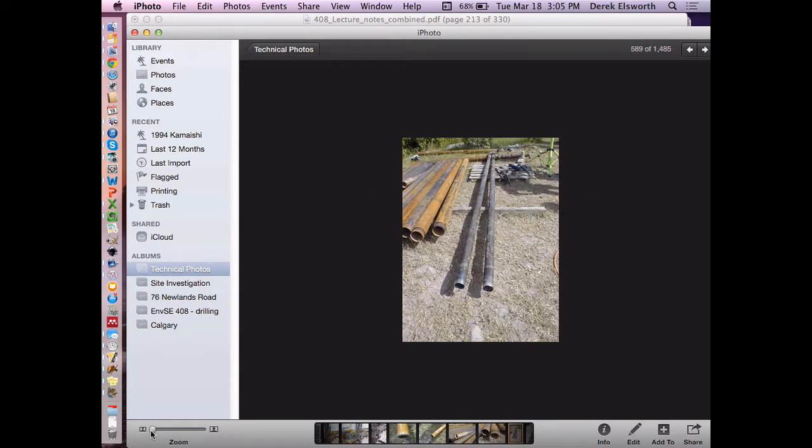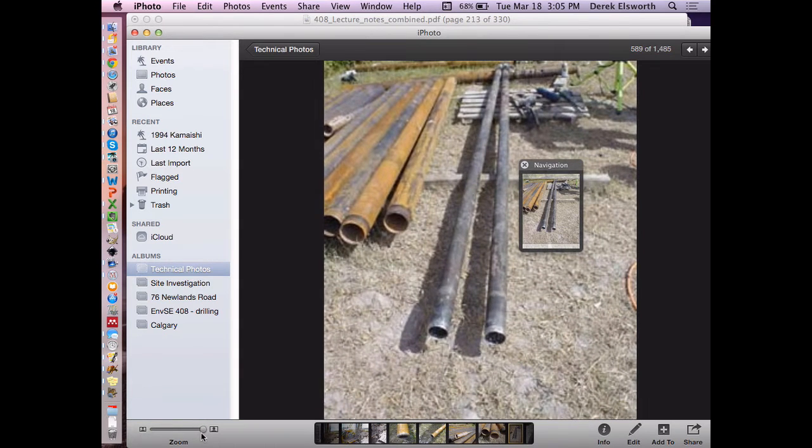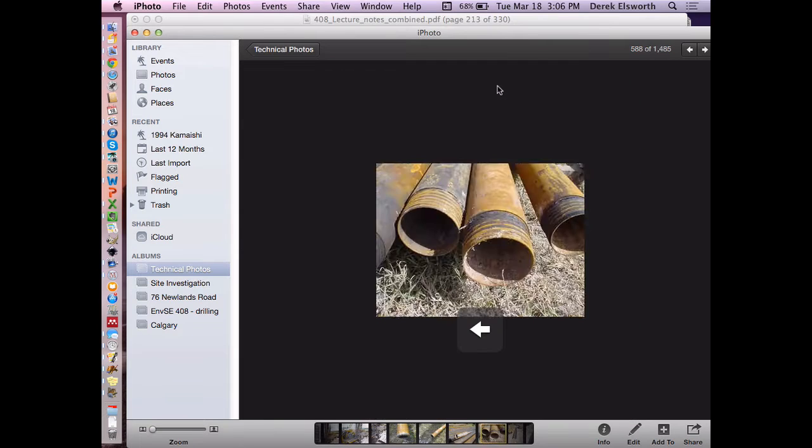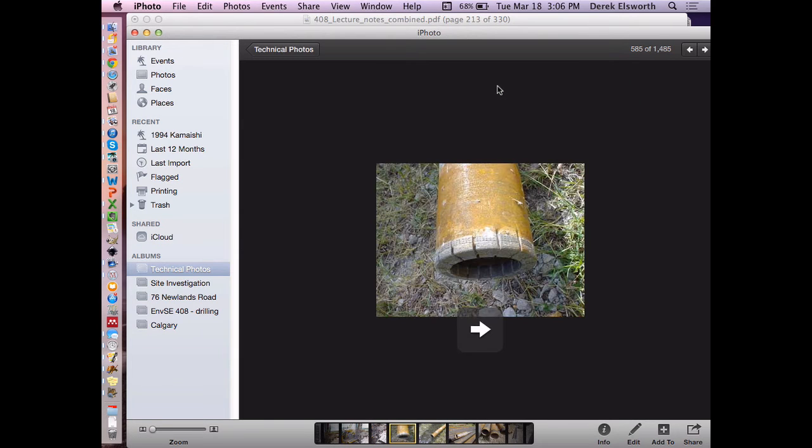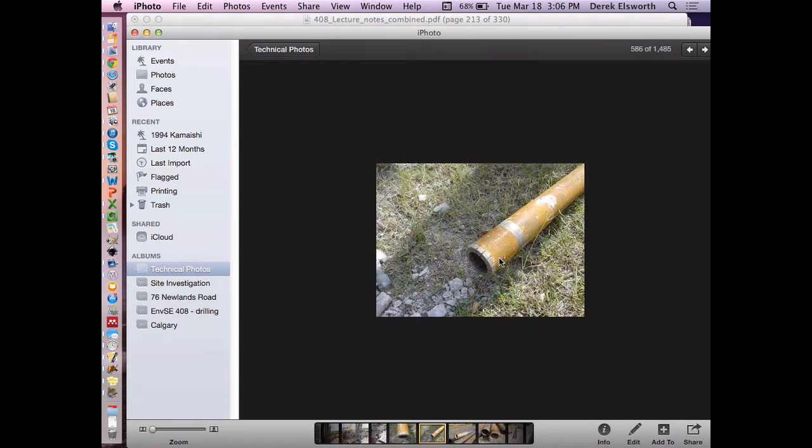When you want to take a sample, what you do is drag a wire line. So this is the wire line. I'm trying to think, this is a few inches across, this is probably 10 feet long. This wire line goes in the bottom of the hole, and the tip of it would be right at the front of the shoe and would go up into that last piece of casing.